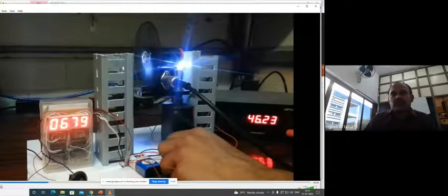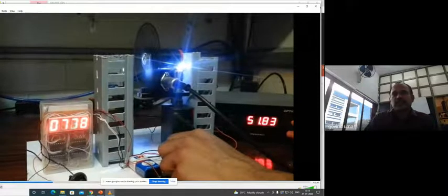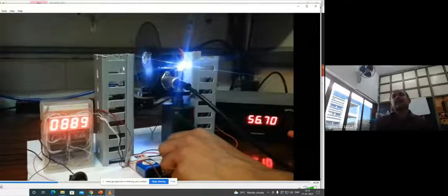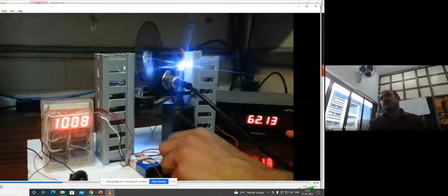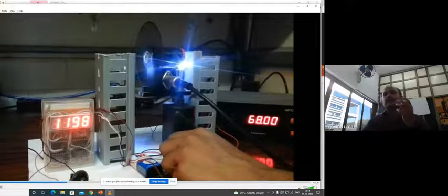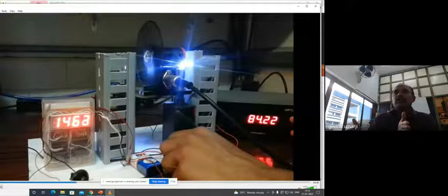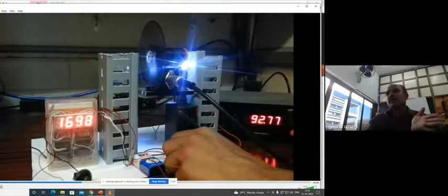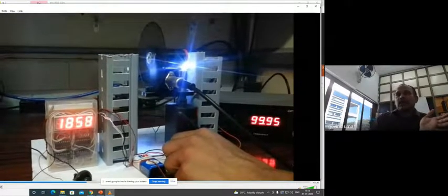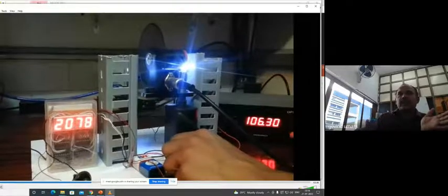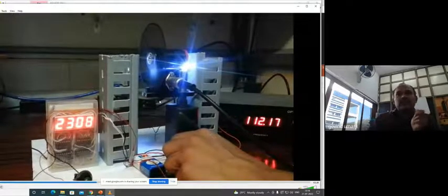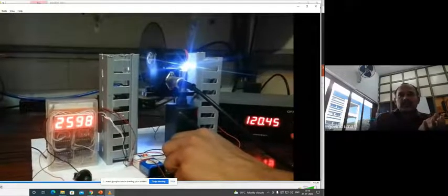A photodiode is conventionally used for such applications, but the photodiode has a limitation: it has a poor signal range. If I want to measure over a long range for a big product in a counting mechanism, the photodiode has a limitation, so we can use this sensor.